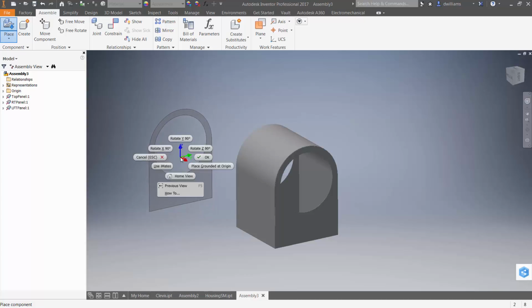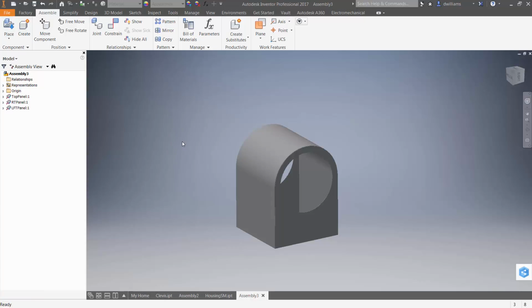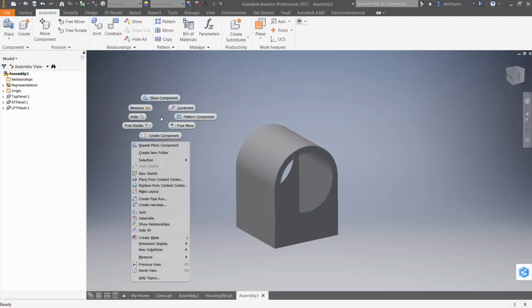Now, this was a slightly more complicated example of creating parts within a skeletal model because it used that derive part functionality. You can actually utilize it in a much more simple fashion by placing any component and then just linking it to the part in a fashion similar to the way that we linked parts to the Excel spreadsheet in the table-driven example.